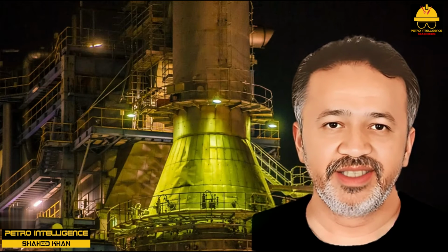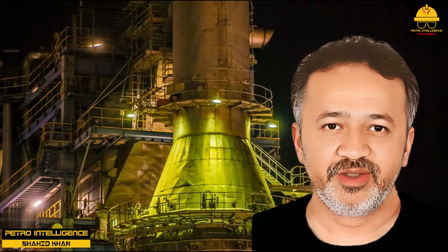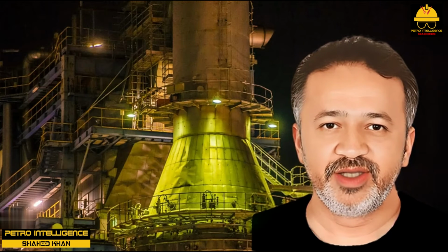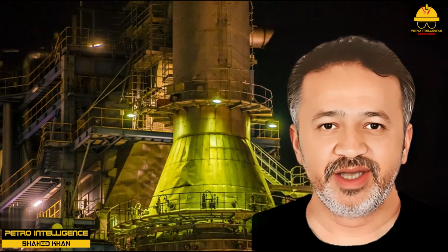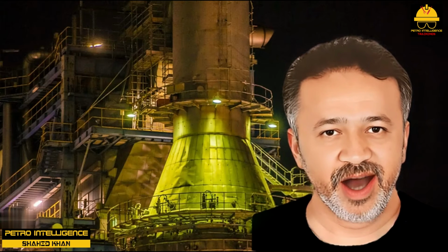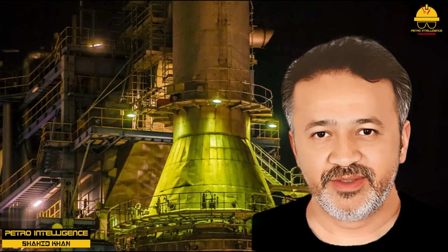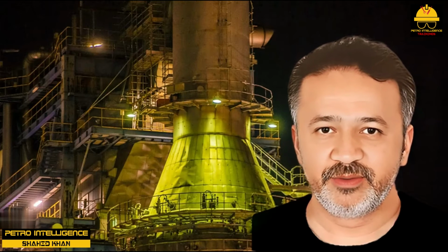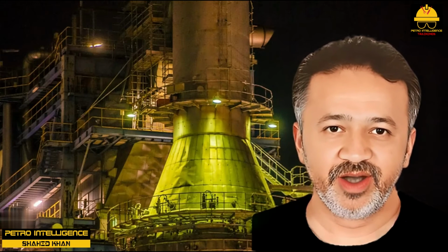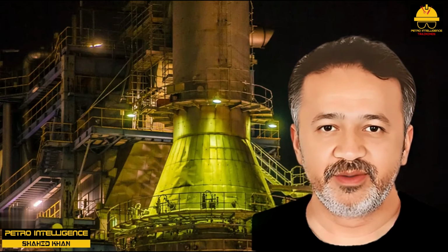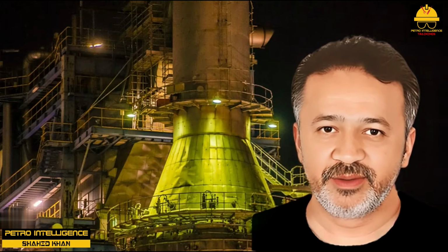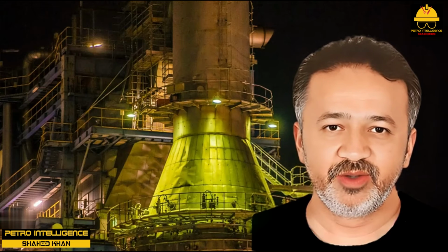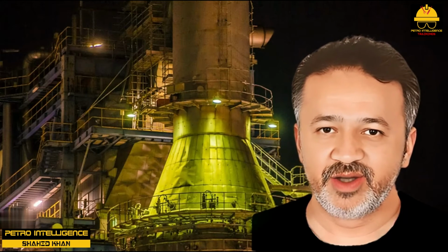At this point, black smoke started coming out of the stack, and several of Operator B's colleagues began to suggest that they should start to open up the air registers and increase the combustion air and not reduce it any further. However, Operator A, now reading 6.5% O2 in the convective section on his O2 analyzer, was determined to reach his 6% O2, and requested a further cut back on the combustion air. When the combustion air was cut back this time, fire started to come out of the stack. Now Operator A was forced to admit that they would have to increase the combustion air again.